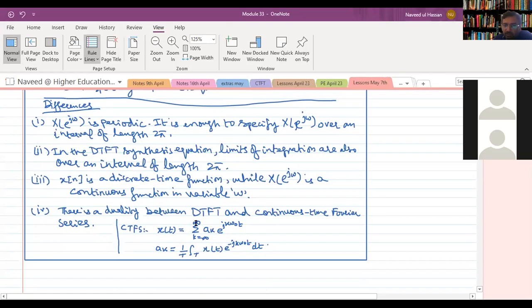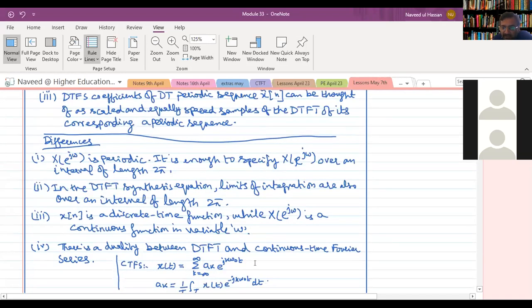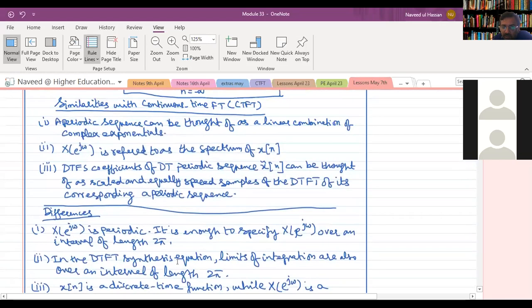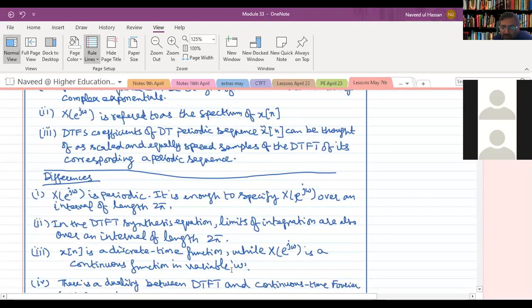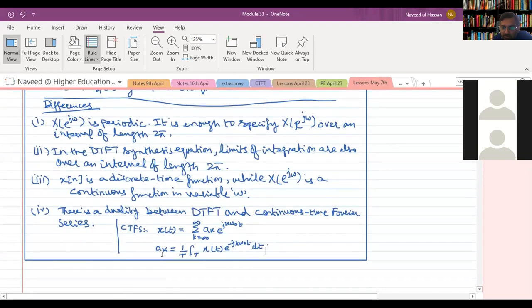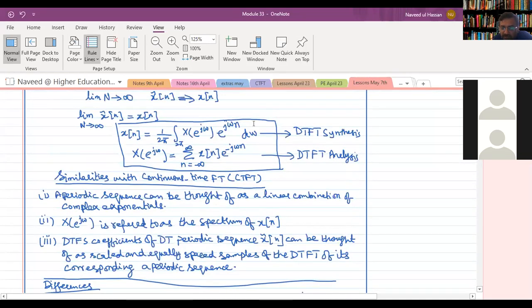Okay, form similar है because यहाँ पे we are expressing x(t) as a sum of these weighted complex exponentials, and x(t) is a periodic signal. तो यहाँ पे capital X e j omega, this function, this looks very similar to this one. और ये जो a k है, its form is very similar to this discrete time Fourier transform synthesis equation, isn't it? Yes, sir. The role of omega and t is reversed, और जो sign है exponentials का वो minus हो गया. That's it. This is the only difference.